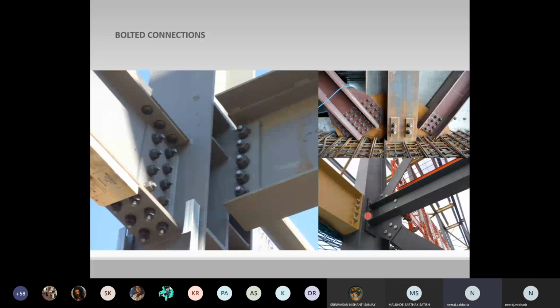So the advantages of these joints is that the process of erection of the structure can be made faster compared to rivets. Skilled labor is not necessary, since if a person is taught the basics of fixing the bolts, then he can continue doing it repetitively. Connections do not involve the noise as it happens in rivets. The requirement of labor is less. Immediately we can use the structure in the case of bolted connection.